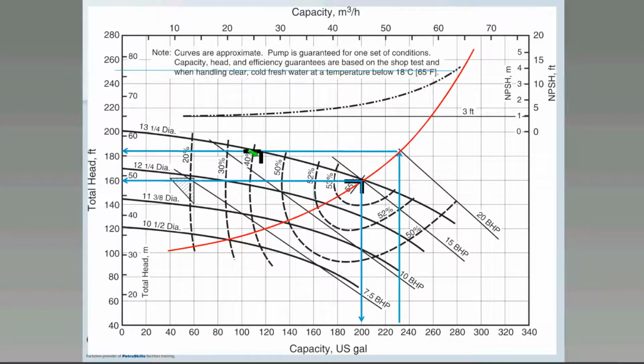And you can see at this point that it is the total head but half the flow rate, which is what we'd expect. So this is why it's so important to have a strong understanding of what the system curve looks like, because you can determine just how much increase in head for that second pump running that you need. Very important. So the other thing that's important to note here is we see that the pump horsepower now has actually decreased. So we've dropped the pump horsepower from about 15 horsepower down to about 12 horsepower.